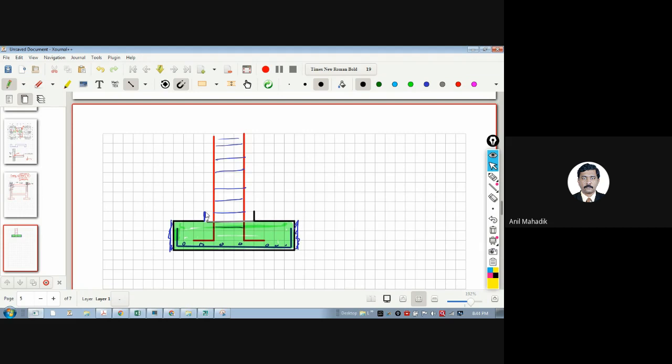The next day, they will do the vertical alignment of the reinforcement correctly by providing some supports like this. They will create this base and do the concreting only within this zone. This is a part of the column, the column dimension. It keeps the cage in vertical position and gives it a base. Once you do this, this side will be smaller, and then again the next day he will put shuttering or formwork here.